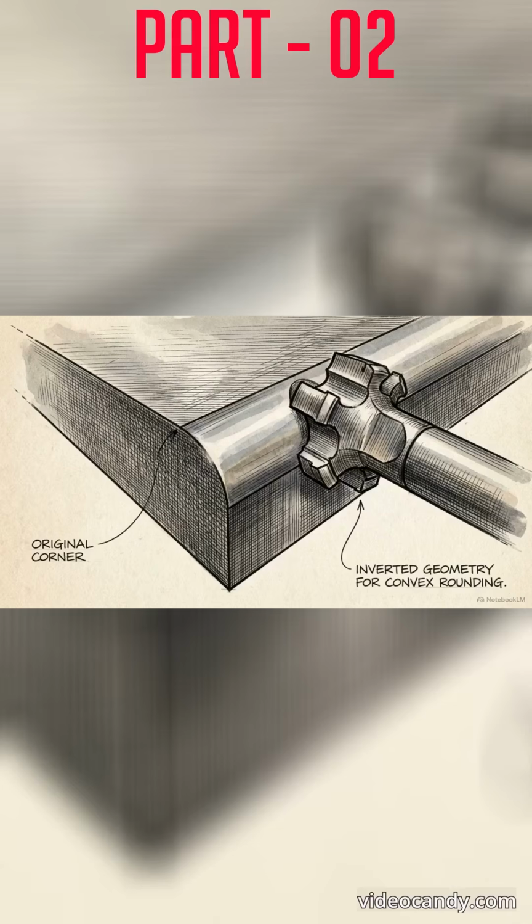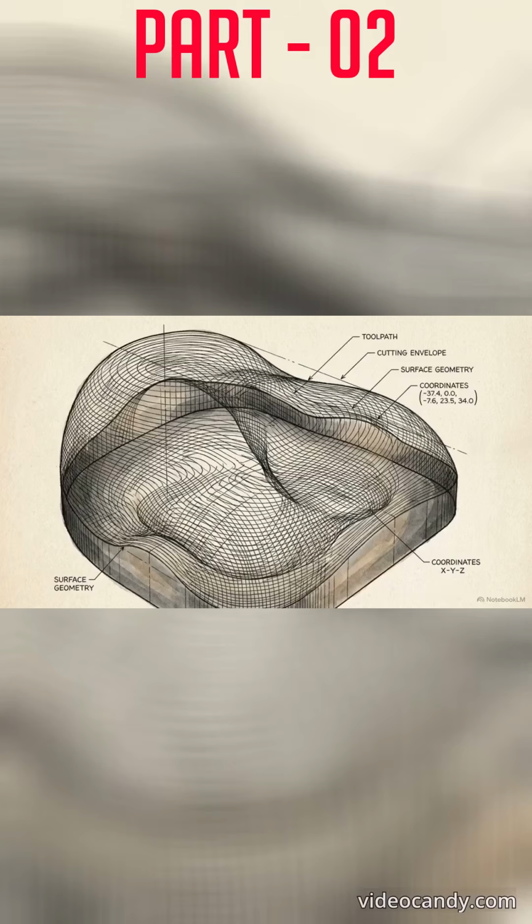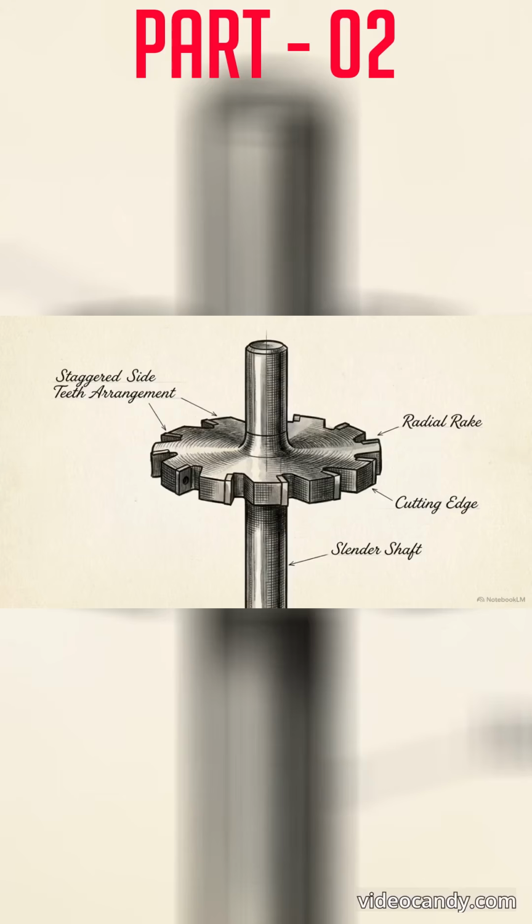Notice how the cutting teeth are curved inward along the circumference to form a strict quarter circle contour. This inverted geometry is the only efficient way to mass-produce perfectly smooth, convex radiuses along the outer edges of a part without relying on slow, complex 3D contouring.